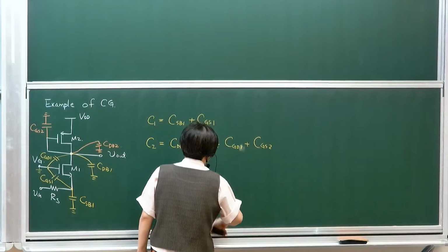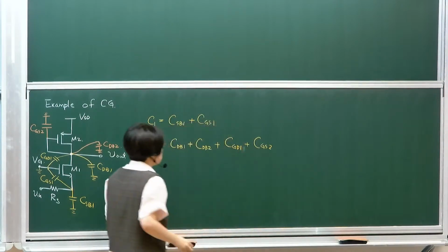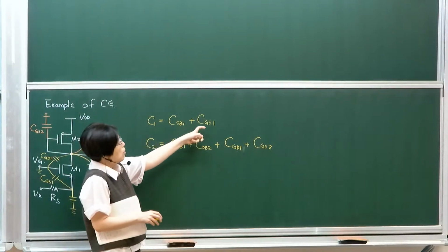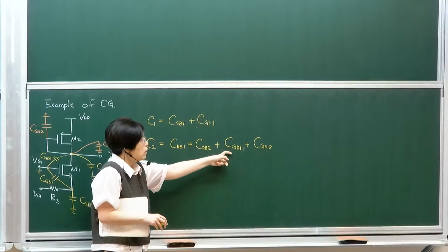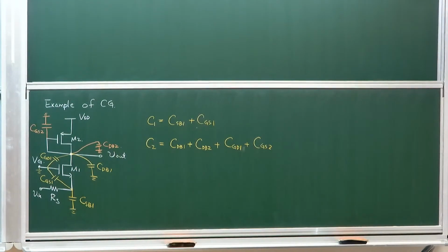Sorry, let me just be precise. I'll separate them into types of capacitance. You start with junction capacitance, because source and drains are junctions, they always come with junction capacitance. And then parallel plate capacitance, gate oxide capacitance, related capacitance.